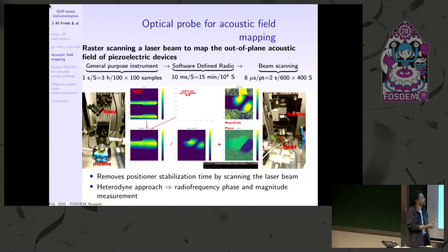It's high throughput data. But then you see that these 10 milliseconds, they're not really related to streaming the data. It's just because I'm wasting time waiting for this positioner to settle. So what about removing the positioner and moving the optical beam? So what we did is we removed the positioner that takes 10 milliseconds to settle, and we just put 2 rotating mirrors. And these rotating mirrors, they have very small inertia. So they will move at 100 hertz. Instead of 10 milliseconds for settling each position, I can get a whole line in 10 milliseconds.